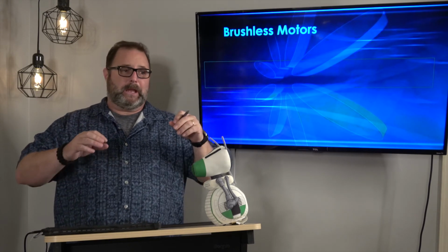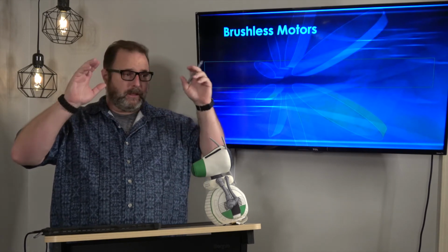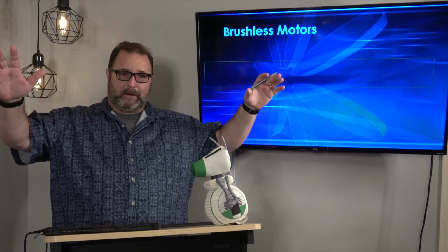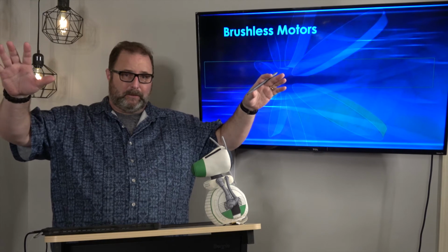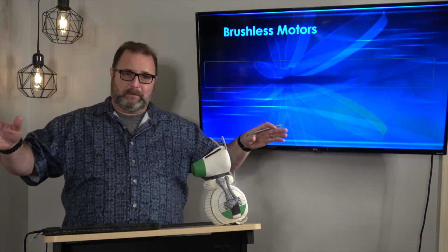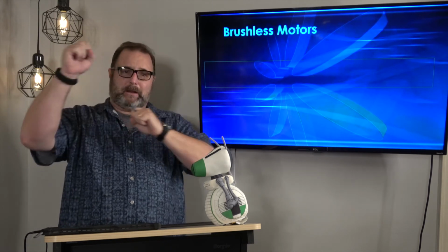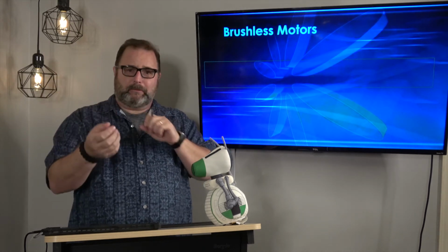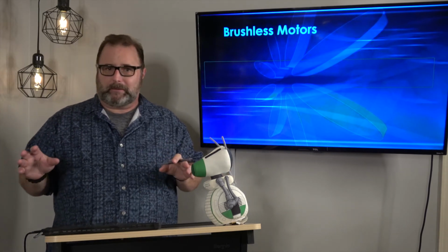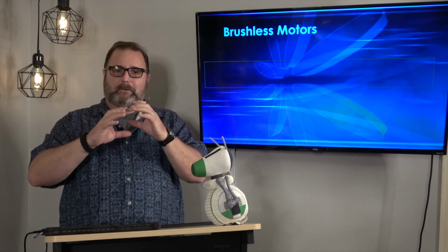So if you're working in an aircraft repair shop and there's an aircraft in there and there's fuel tanks around, you can't use a brushed motor for any power tool. They're in there with hand crank drill bit drivers to take screws out because you don't want sparks anywhere near a fuel tank, okay? And brushed motors create sparks.